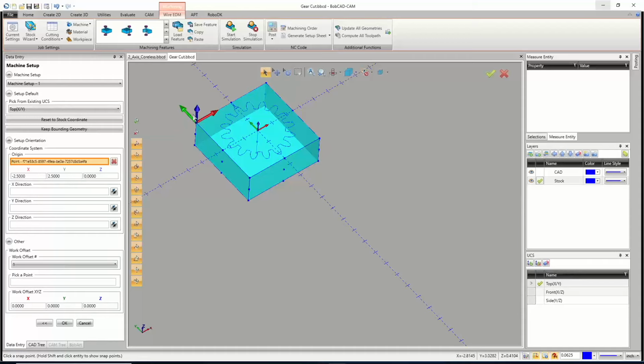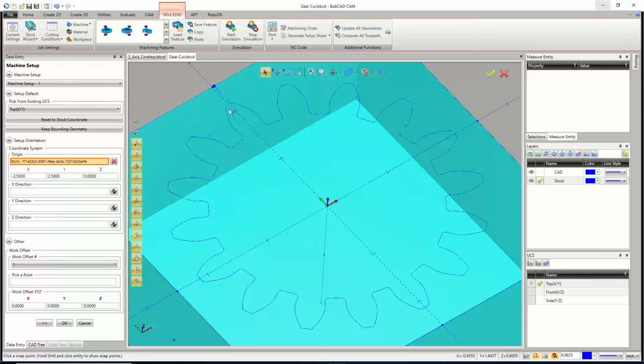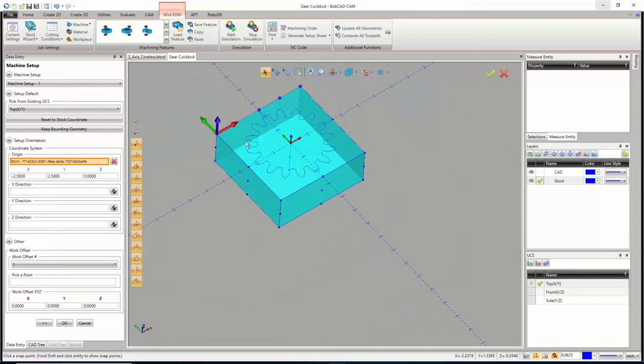It's pretty close to my start point, so I could do some math to figure out, reading through the code, where this start point is right over here, so that's not too bad. So I'll just leave it right there in the corner. But again, you can pick wherever you need, wherever you're going to be zeroing out from. Some machines, you'll have to pick the bottom point on the stock. You'll have to pick a point down here, and then you're going to define the height upwards. But I'm going to go from the top down right there.